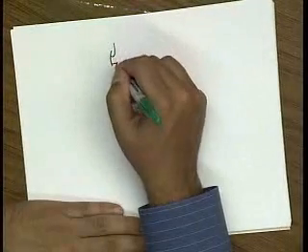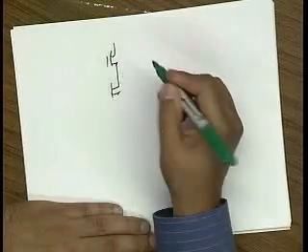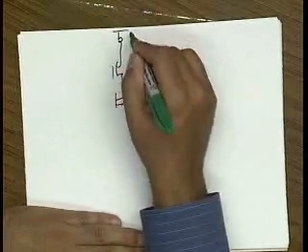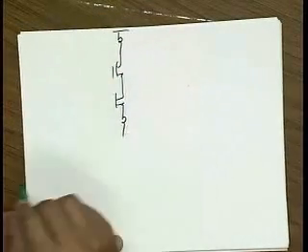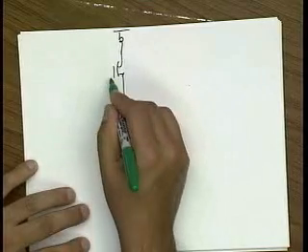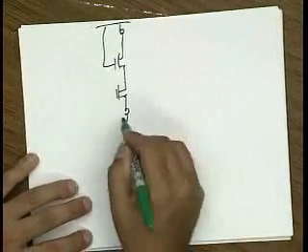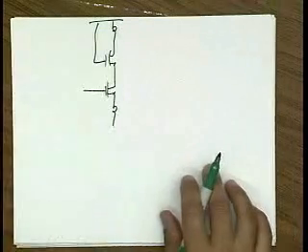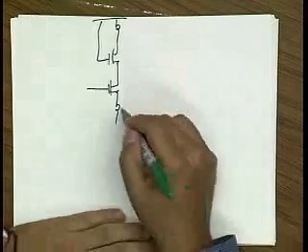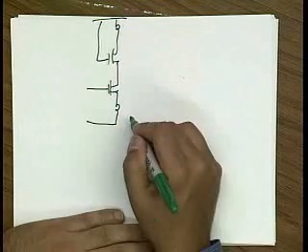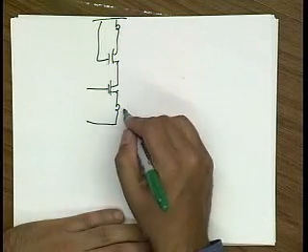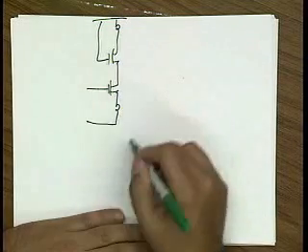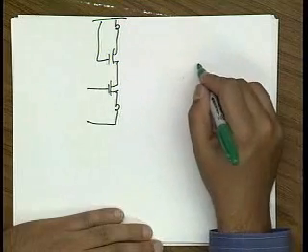So that's pretty much, if you look at the workhorse CMOS LNA, it's basically what we've just seen. It's an inductively degenerated device. And the next question is, how do you actually build this inductor? So we said that you could use bond wires. If this inductor needs to be larger than the bond wire inductance, you actually can realize this in many parts. So let me try to draw a layout here.